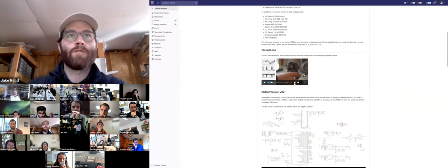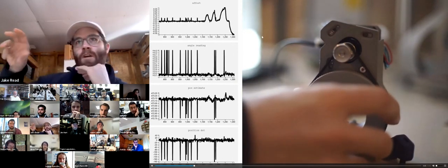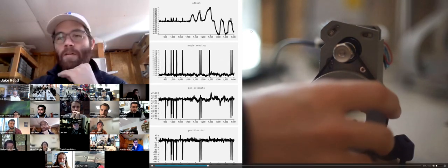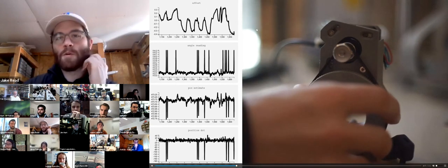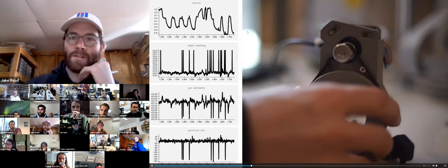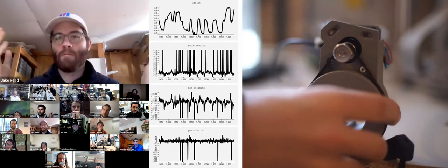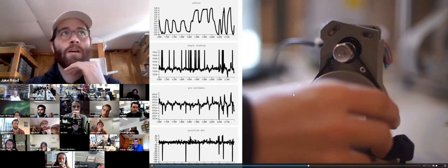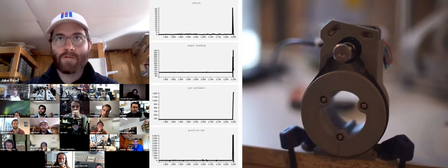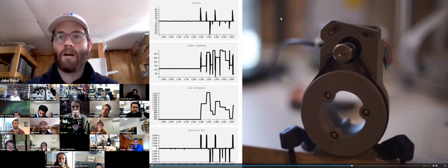And then, yeah, for controls, I've recently woken this project up again. This is a stepper motor, but it's controlled in closed loop. You can see in the top left here, as I'm exerting a little bit of force on the motor, it's reading out the effort that it's using to control position. Especially with newer motion control work we've done for modular things, we now have a really good framework to start integrating this kind of learned motor models into motion control models. Actually just this week, I've been playing with this again to see if we can automatically build torque curves for motors. Here it is positioning in closed loop. And then use those torque curves in our acceleration controllers.